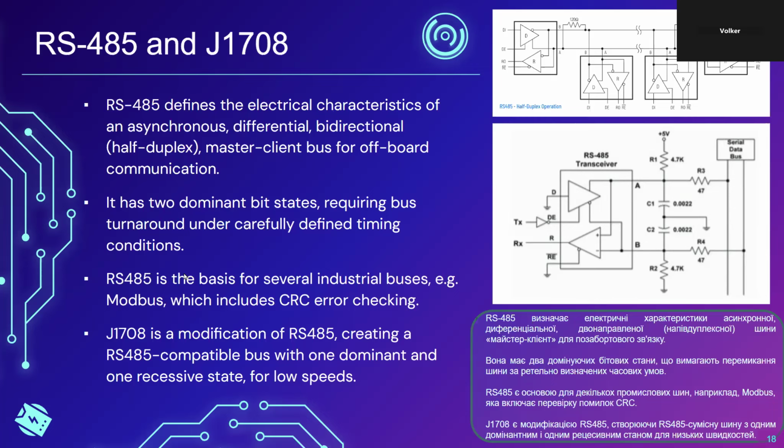Basically, after the last stop bit has been clocked out, right away the transmit driver needs to be disabled and the transceiver needs to be put into receive mode. So in order to avoid bus collisions, that is a timing problem.